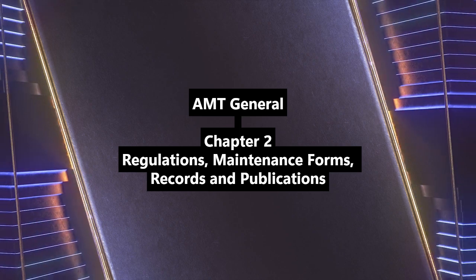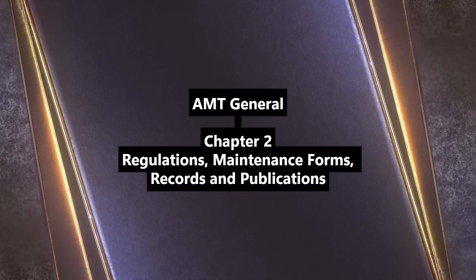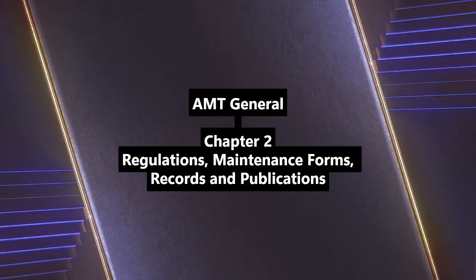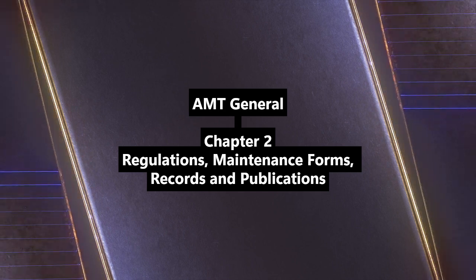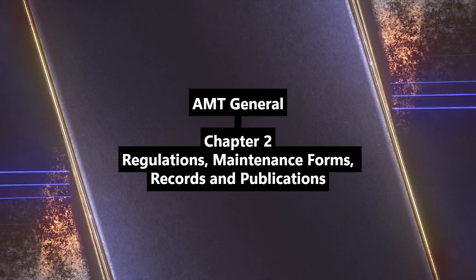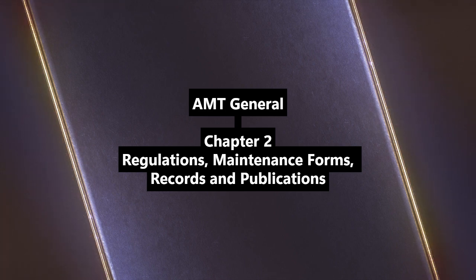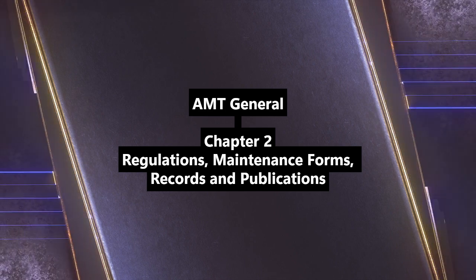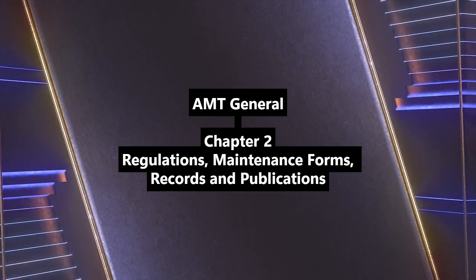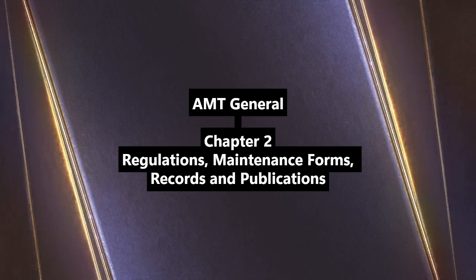Extremely. English manual with descriptions, operating info, servicing, maintenance instructions, schedules, tolerances, overhaul periods, inspection programs, troubleshooting, removal, replacement, testing, diagrams, special techniques, fasteners, special tools, everything. Plus that mandatory airworthiness limitation section. Critically important. Mandatory replacement time, structural inspections. Technicians must have current, correct data and tools or risk violating regs like 43.13(a) and 43.16.